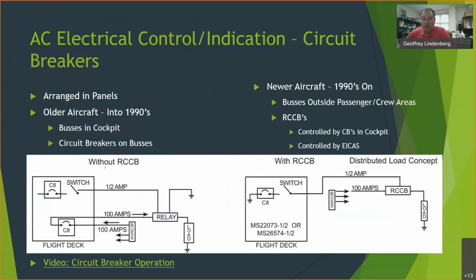So once we've got our electrical control, our big breakers, now all those switches are going to move different circuit breakers and contactors and that kind of thing. And what we had back in the day is all the controls were run up in the flight deck. You look in, say, our 727, for instance, and behind the flight engineer's panel, there's that big panel of breakers, and over the spotter or over the observer seats, there's another panel of breakers.